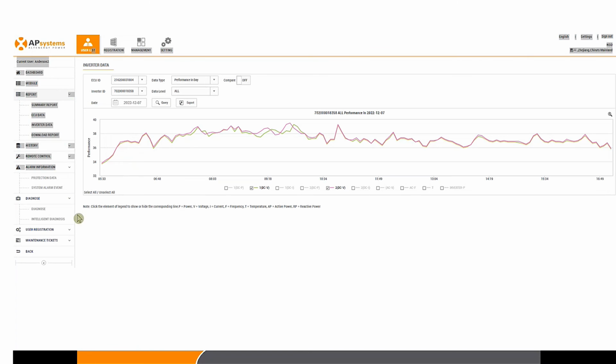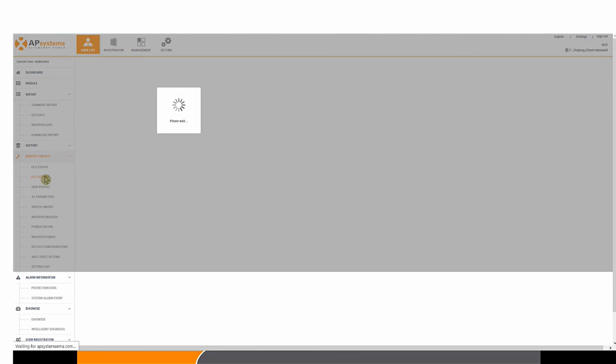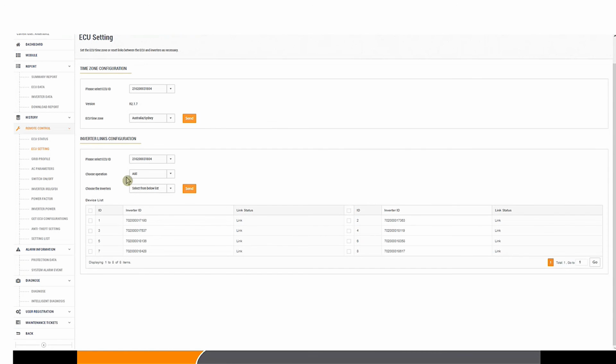Now just be mindful. I'm going to show you another thing, and I think this is going to be the last one as well. A couple of things you also want to check is that you go to ECU setting, make sure you've linked everything, and make sure a link is all here. Sometimes the panel shows 0 because you forgot to link them. Like I said, when you create the account, the installers may sometimes forget to click the link button. So if they haven't linked it, just simply click on those, and press send, and that links the inverters. But in this case, it's already linked.